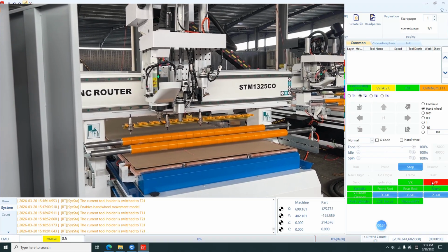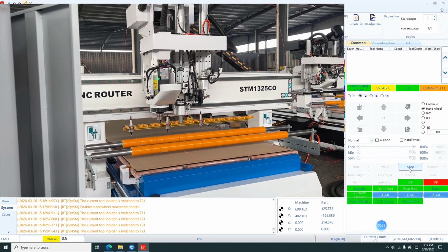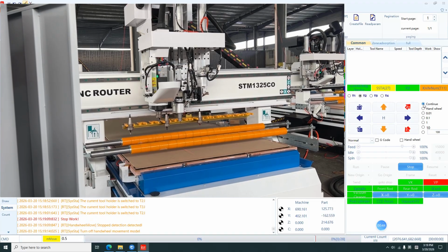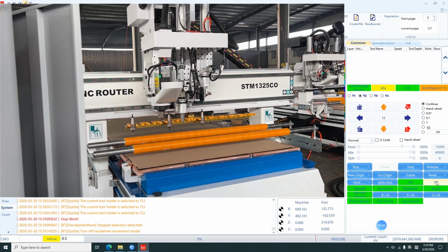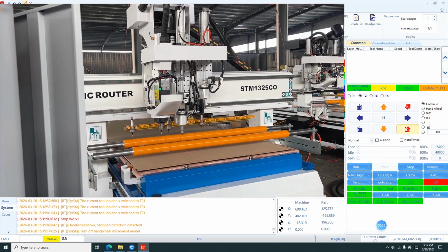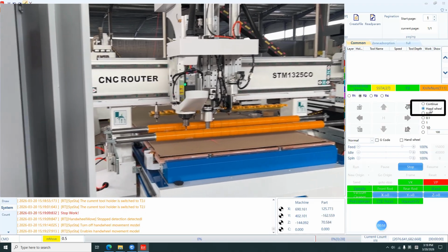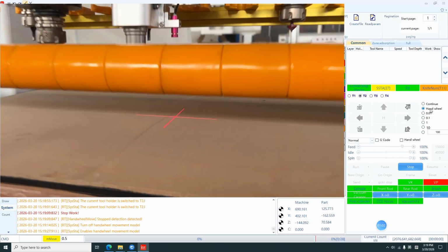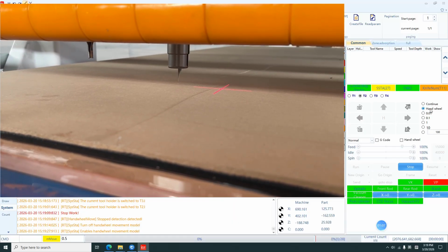Lower T2 oscillating knife. Start the vacuum pump. Set the Z-axis 0-point position for the blade to begin cutting. The vacuum pump is activated to ensure greater accuracy in the Z-axis cutting depth. In continue mode, the vacuum pump can be manually activated. Enable the hand wheel function. This allows for fine-tuning of the X, Y, and Z axes, making height adjustment safer.